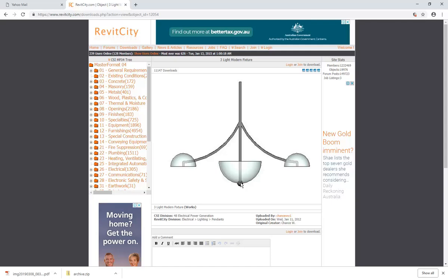So the better way, the way I do track lighting, instead of trying to do it with one family, I'll have a light family that is the thing that's on the track, and I'll copy that and have 4 of them, and then I'll just model the track as a separate thing, instead of trying to do it as one family.